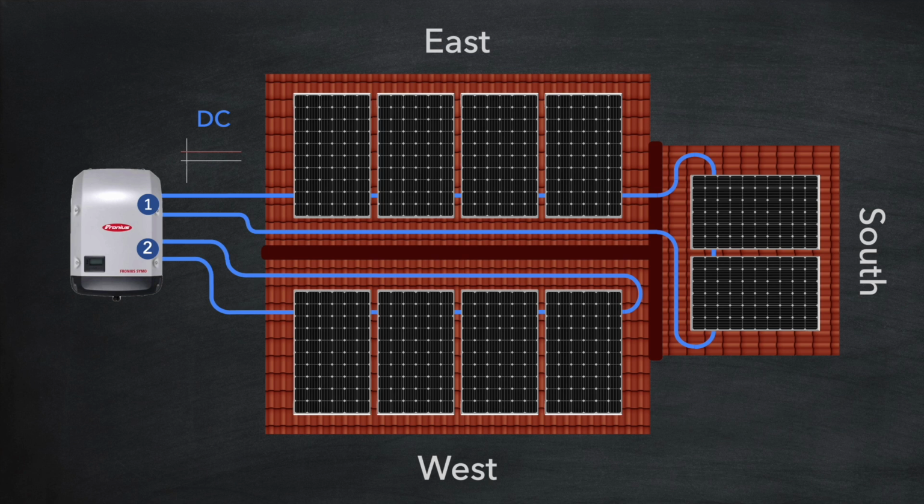Another way is to keep the current inverter and use optimizers on all the panels in string 1, like so. These optimizers should easily be able to manage the differences in generation between the east-facing and south-facing panels. In fact, it's one of their biggest selling points. Each optimizer performs its own maximum power point tracking for the panel it is managing. So if there are differences in generation across the panels, the optimizers are able to work around that in order to retain the highest possible power output.